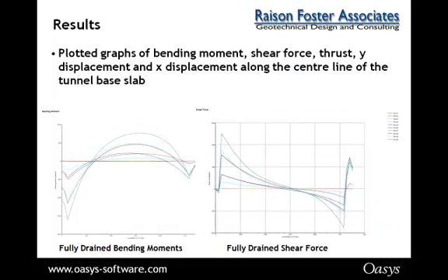And in terms of its outputs, SAFE is able to take various sections through the different problems. But I've just focused on the one here where we've taken sections through the base slab, and we've looked at the bending moments and the shear force at different points in the construction stages. So as you can see, you can plot the graphs out, you can show it to clients or present it in your report. But another thing that SAFE is able to do is that it's able to pick specific displacements and forces at points of interest along the base slab.